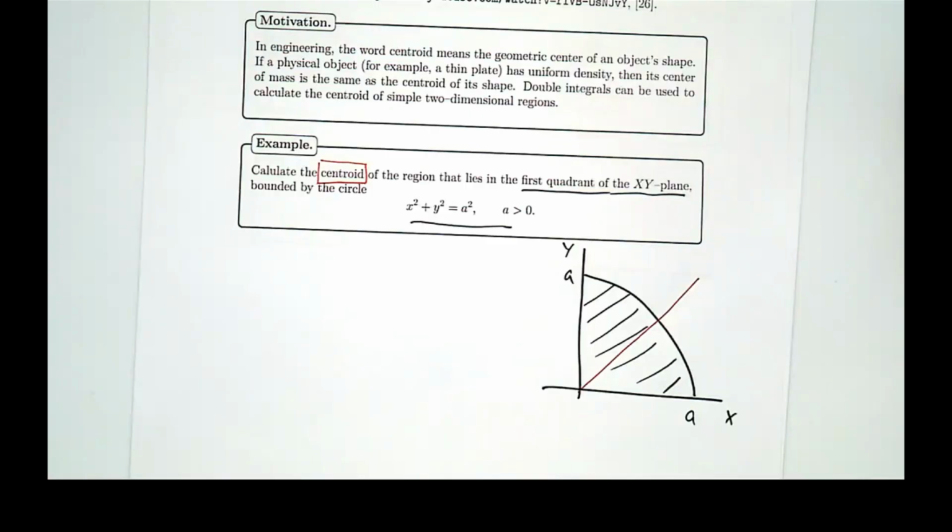So for these kinds of problems with centroids, center of mass, center of area, whatever, if it's symmetrical, the points lie on lines of symmetry. Okay? So this can be a huge time saver. You don't actually have to go through and calculate all the double integrals or whatever it is, if you can see the symmetry.